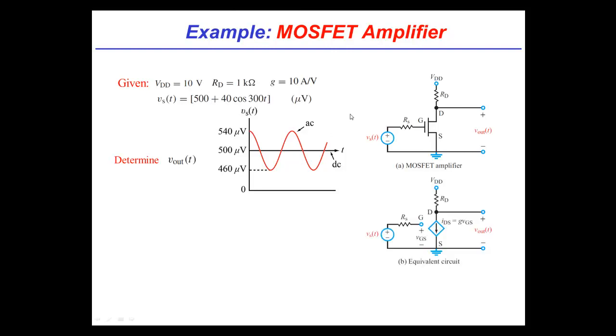All right. So let's go ahead and replace this transistor by the equivalent circuit that Michelle introduced before. Again, you'll notice that the gate terminal essentially behaves completely isolated, so there's no current through the gate. And then we've got this voltage-controlled current source shown over here. Okay, so what's the output? Well, the output voltage is just going to be VDD minus the voltage drop across the resistor. So that's VDD minus IDS times RD.